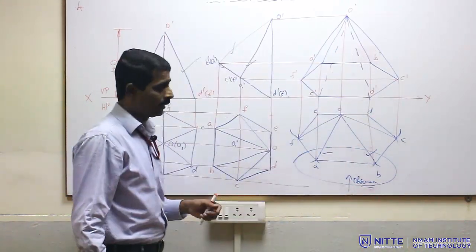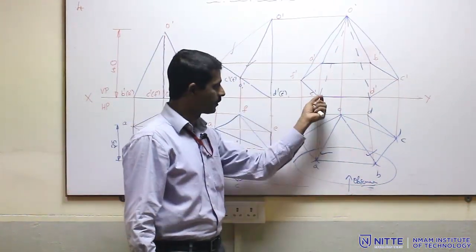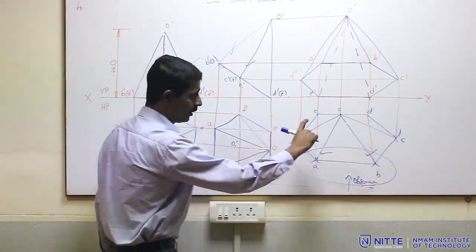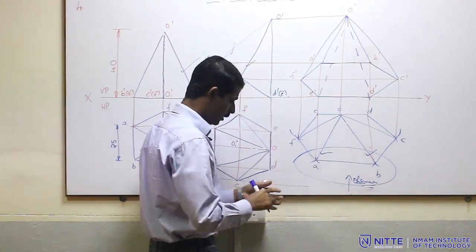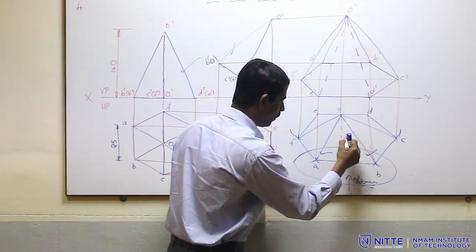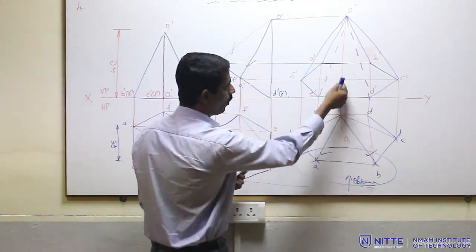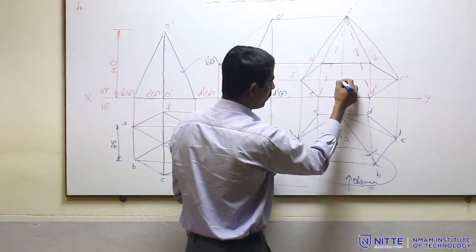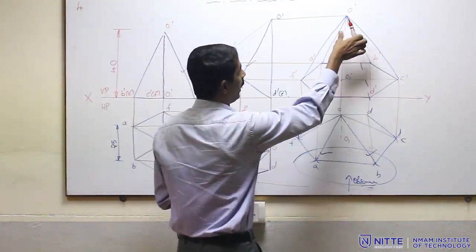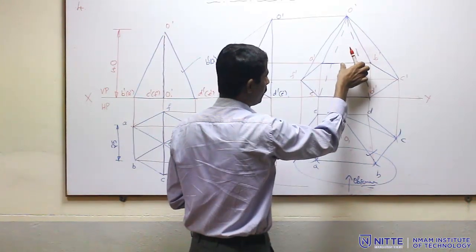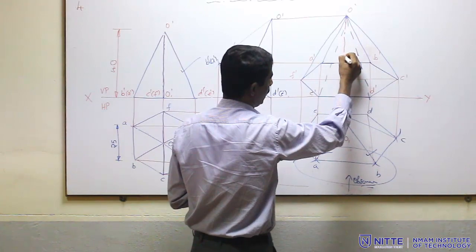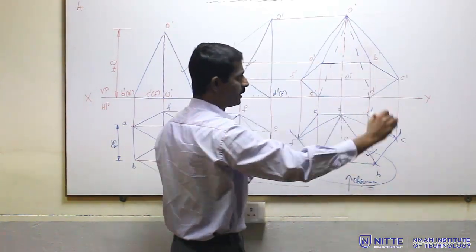Okay, hidden. And the last, to complete the problem, I am supposed to draw the axis. So, here this is the axis O dash O1 dash. I am supposed to draw it here. I will go with red color. Okay, this was O1. So, I projected O1 here, projected O1 dash here. This is O1 dash. Okay, that is O1 dash, and this particular part of the line is the axis. So, I must take axis line type and draw a line this way.